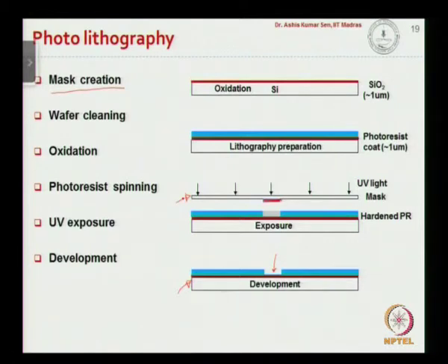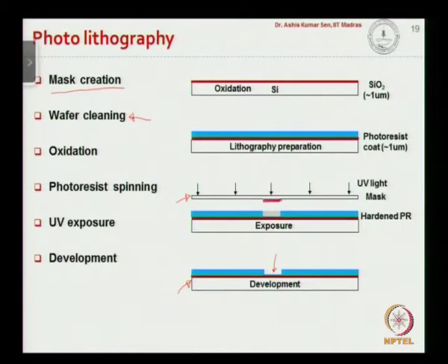Then the first step it starts with is wafer cleaning, where we try to clean the wafer, make sure that it is free from dirt, dust, any organic deposits, and is perfectly clean, so that the photoresist adheres perfectly well to the surface. So we start with wafer cleaning.